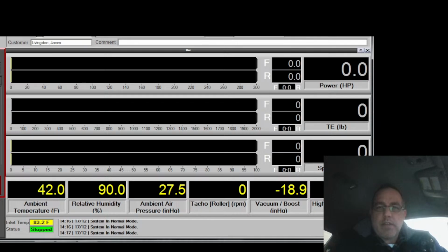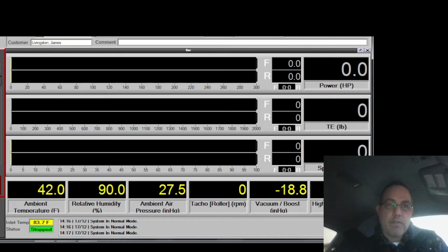All right, so I need more idle air. This thing is not flaring. I want to flare more when I start the car. Let's do this. Let's do that. That should flare a little more. Okay, let's save that. And then let's bring up